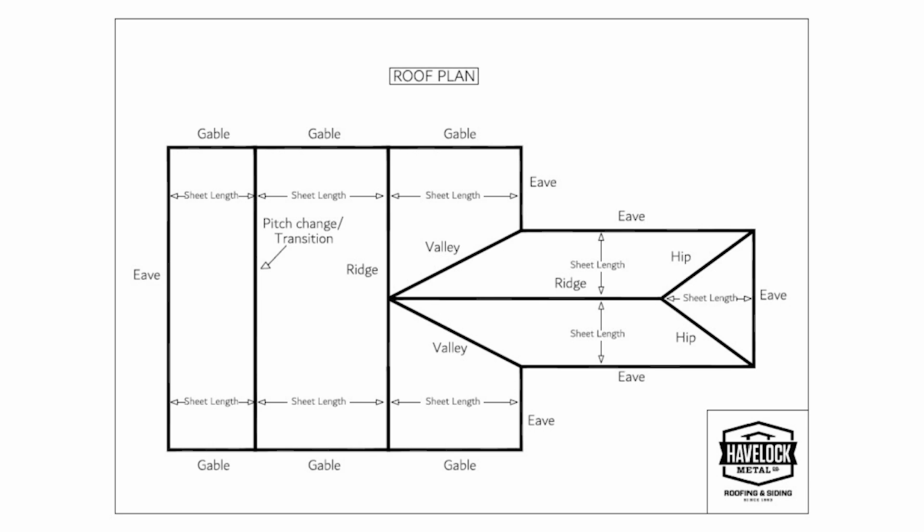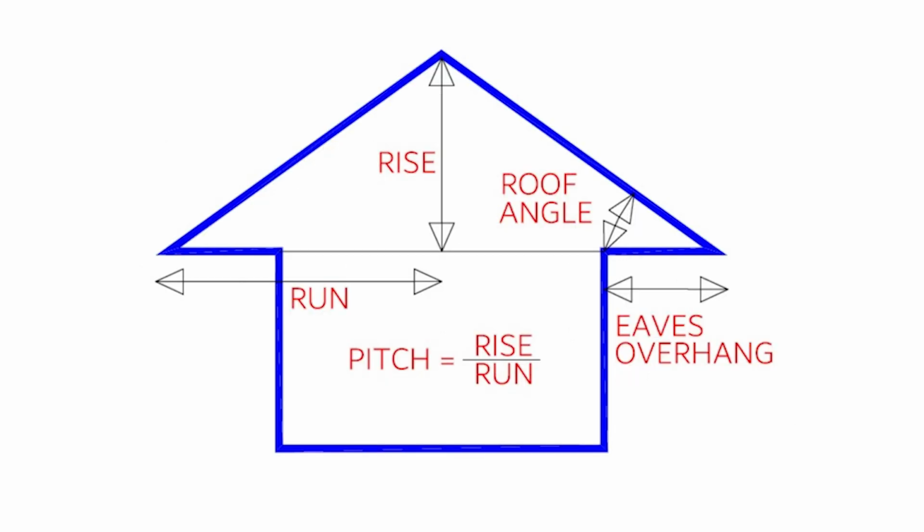Not sure how to calculate that? It is simply a rise over run consideration, meaning over a 12-inch run on any horizontal plane, how many inches does the roof rise? We bend your trims to match the pitch of your roof to create a better finished look and make the installation easier. Still not confident on how to determine pitch? Here's an even easier technique. Download a slope finder on any smartphone. They exist and usually are free.